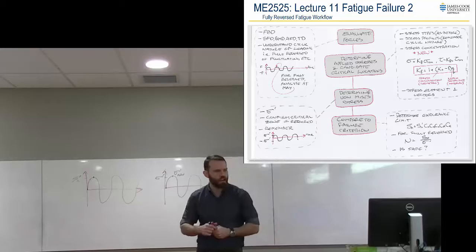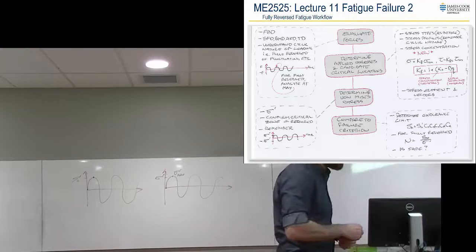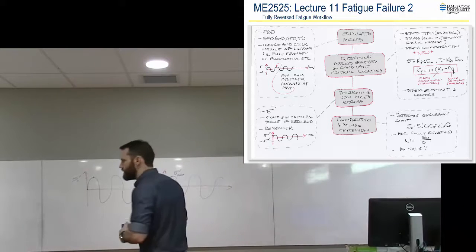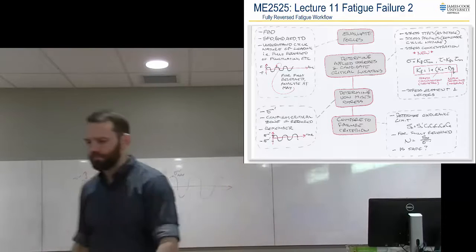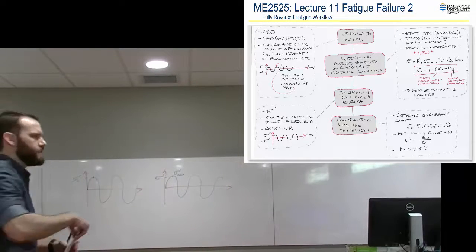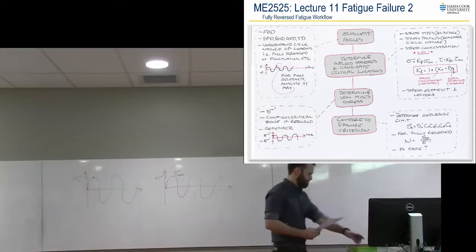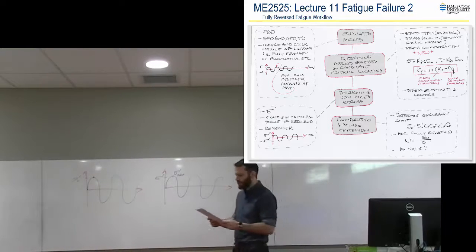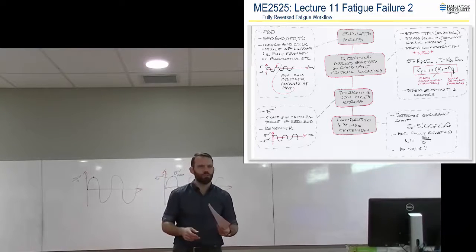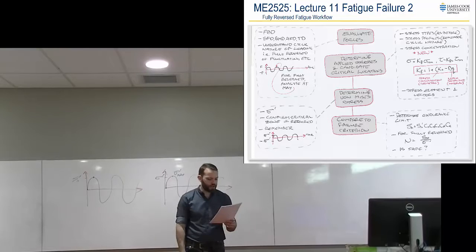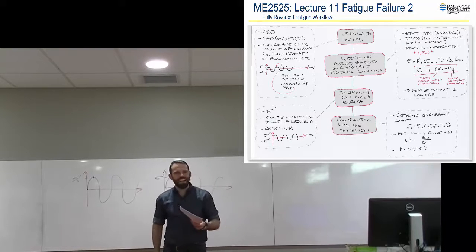Everyone look at your handout, the endurance limit modifying factor handout with the 4 tables and so forth on it. Right, the bottom 2 graphs. The bottom 2 graphs are your notch sensitivity. Now, if you look at that and you actually read the headings rather than just use the table blindly, the bottom left one is notch sensitivity charts for steels and 2024-T wrought aluminium alloys subject to reverse bending or reverse axial loads. So the bottom left one is bending and axial.